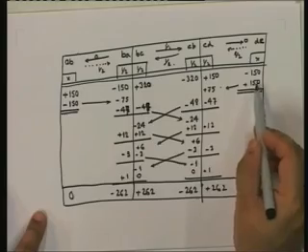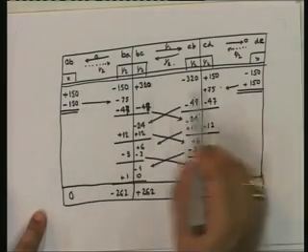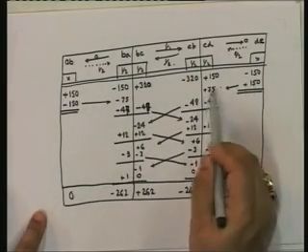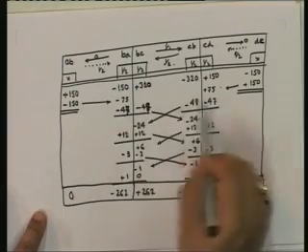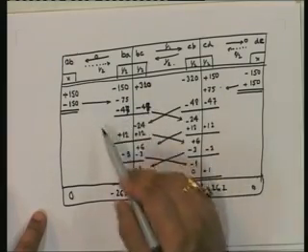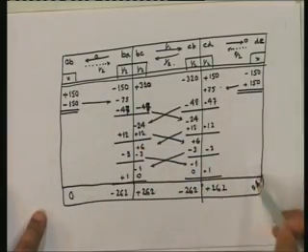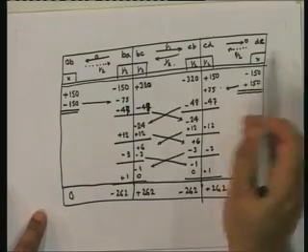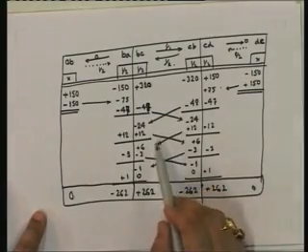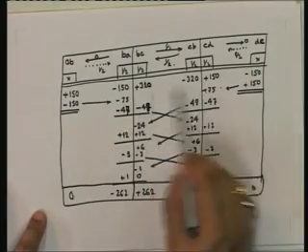So, the first thing that we do is actually release the two end releases and carry that over once only, and that's it. Then these two are finished because now nothing goes back to them. Okay. So, now what we have to do is we look at both the members.